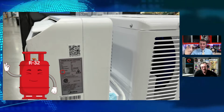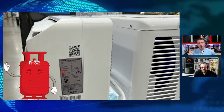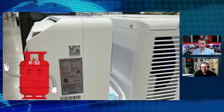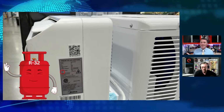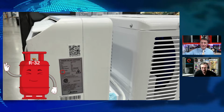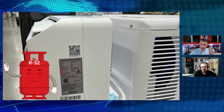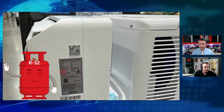So this is me walking through Costco about 3 weeks ago, right? So this is a window unit. Have you noticed any changes to it? It does look different. It does, because we have now isolated the evaporator and the condenser. So our window is going to slide down in between the unit. What does that do? It isolates our refrigerant network. Where's most of our refrigerant at? Outdoor, right? Indoor is hopefully primarily vapor, right? So as we're boiling off in our evaporator, we should have a majority of our refrigerant outdoors, not as much on our indoor unit. Again, these are smaller charge package window units.